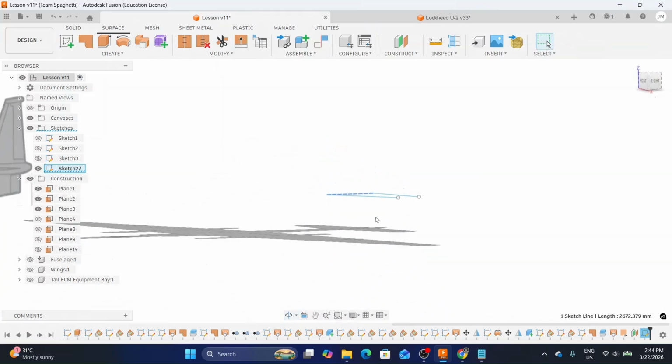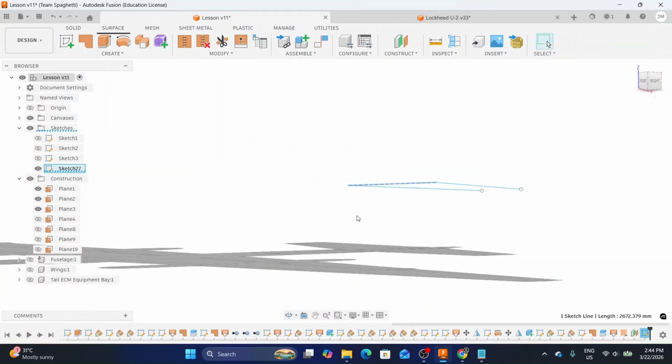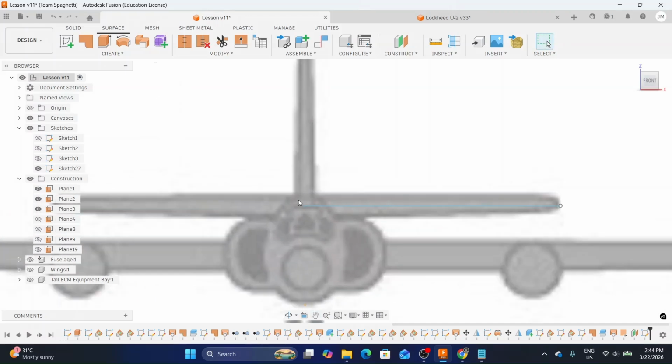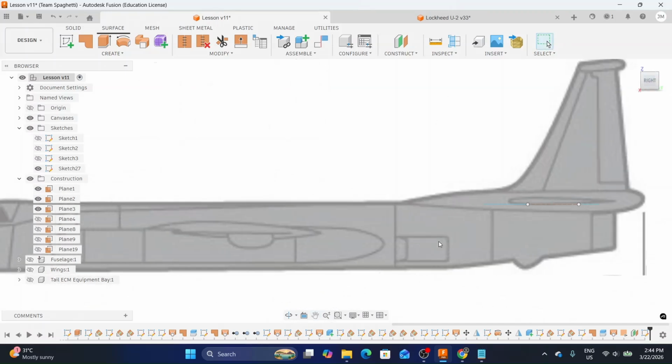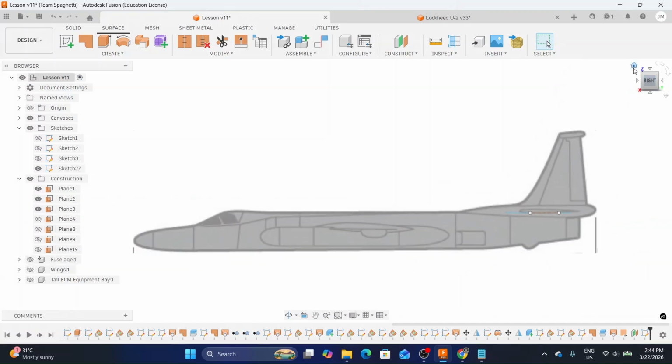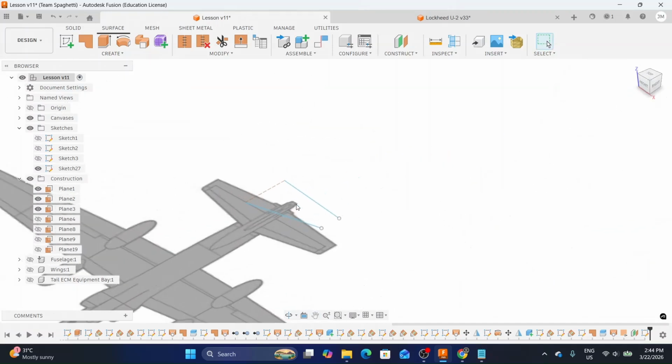Next, we could see here that the sketch is created from the plane that we have offset, and then let me just visualize it. Make sure that this is correct. Okay, that is okay for me. And the next is I'll create a plane at an angle on this construction line.